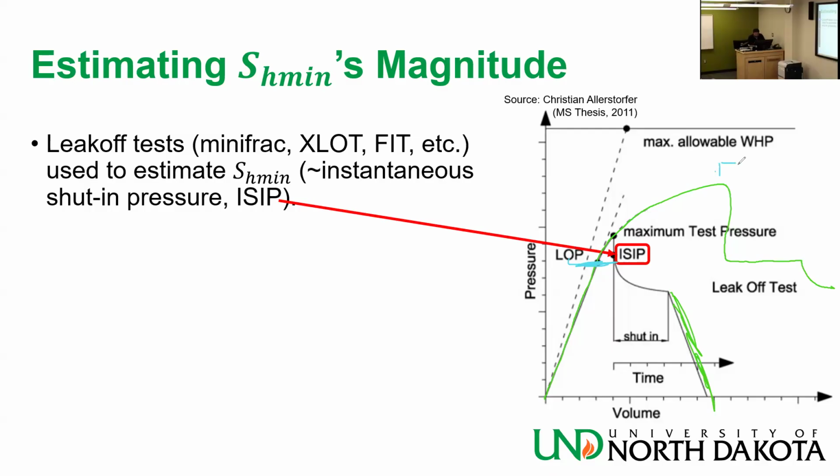This is called FBP, formation breakdown pressure. That's the highest pressure the well will ever see. Okay? So if you are trying to test the well integrity, you are looking at FBP. You want everything to work well when the well is at FBP.